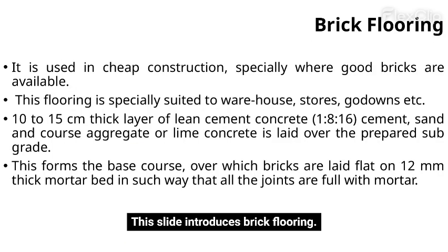This slide introduces brick flooring. It's a cost-effective option, especially where bricks are readily available. It's well suited for warehouses and stores. Construction involves laying a 10 to 15 cm layer of lean cement or lime concrete as a base, followed by bricks laid flat on a mortar bed.